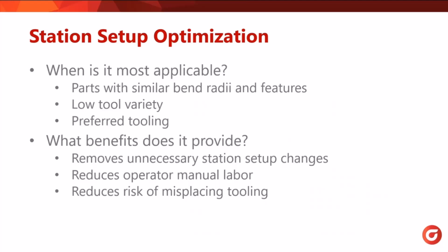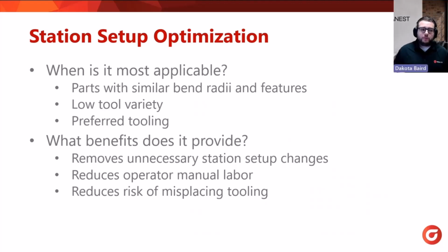So when we look at this type of feature, this is really most applicable to customers with lots of similar parts. So obviously you need to be reusing the same tooling in order to do this. So if you have lots of parts with similar bend radii or similar features, this station optimization tool is a lot more beneficial or applicable to you. It can save you a lot more time. It's also more applicable to people with lower tool variety, right?